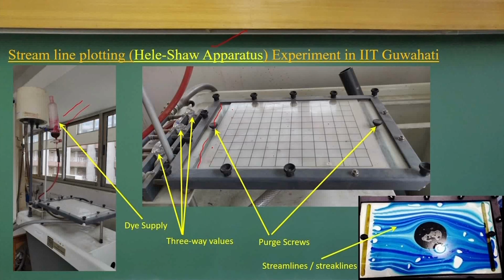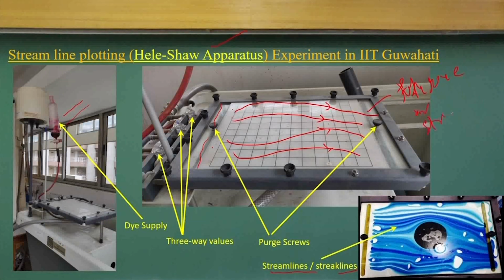As we make the flow steady, the streamline and streak line, when you look at it, if I put the color dye, this will show me the streak lines or the path lines, if I am tracing that, okay, path line or streak line, or since it is a steady flow, I can tell you that it is a streamline.